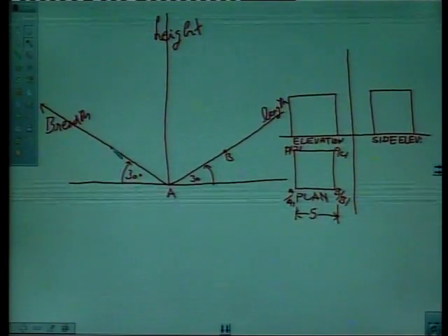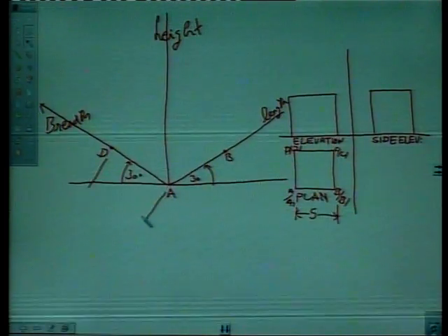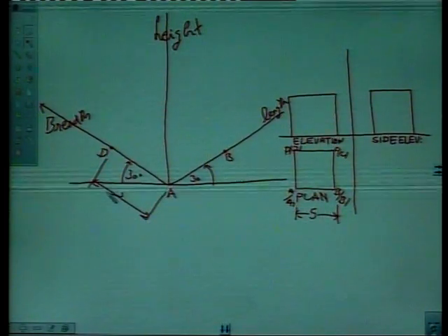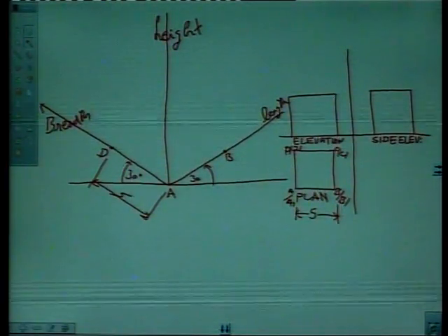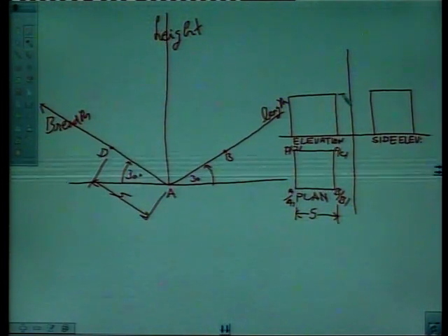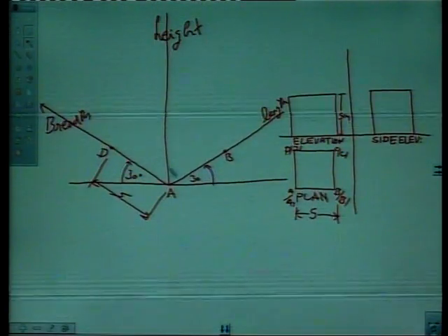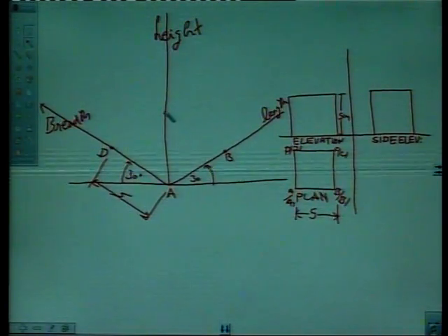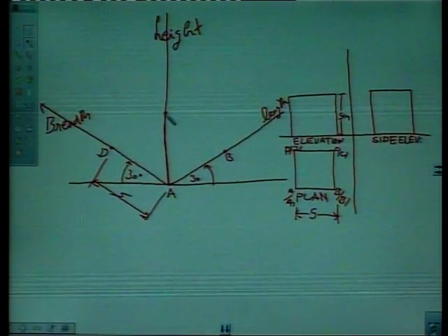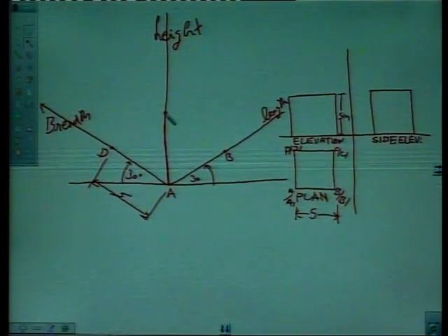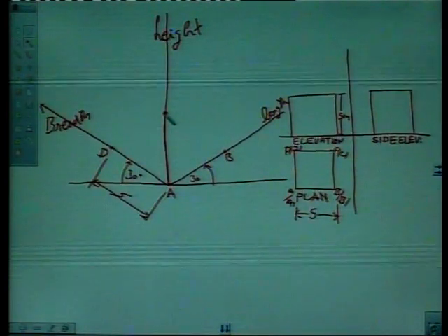So this is again A to D, 5 centimeter. Similarly, height of the cube is also 5 centimeter. So mark height here. Right. Now we have the length, breadth and height of the cube all marked on the length, breadth and height lines.